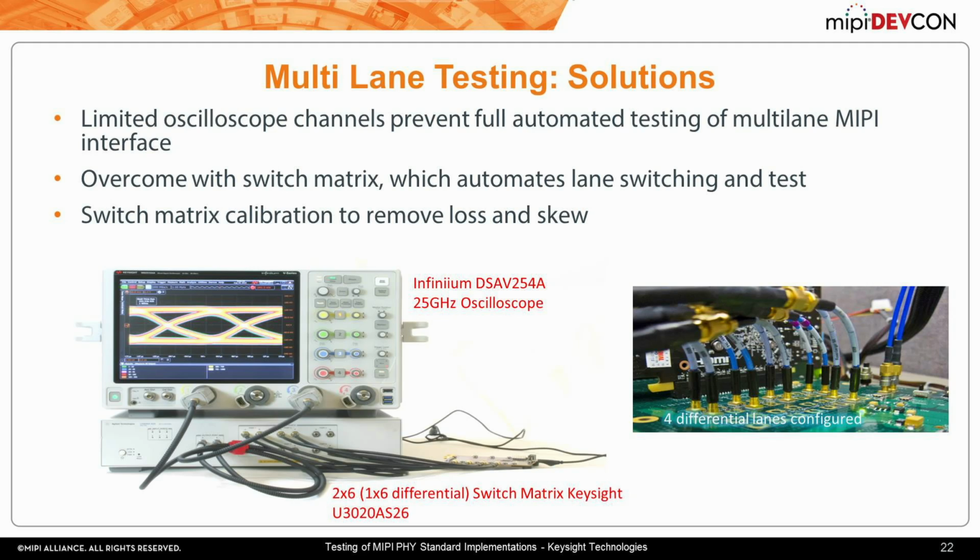You can think of it as a high-pass filter, and your high-frequency components are getting boosted, but not only to compensate for the loss here, but also your scope's high-frequency signal components, the noise that is inherent in every measurement instrument also gets boosted as well. And at some point, that noise, if we have enough compensation, becomes very significant, and you start to have some impairments from this de-embedding process itself.